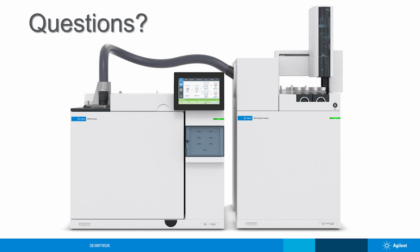Volatiles are prevalent in a lot of different areas, so you have to make sure that your sample prep station is clear from volatiles. Something I would recommend is to cap some vials that are left out in ambient air and analyze them to make sure you don't have volatiles in your ambient environment. We see issues with this. At one point, we were prepping our volatile standards right next to a solvent cabinet and getting really strange results.